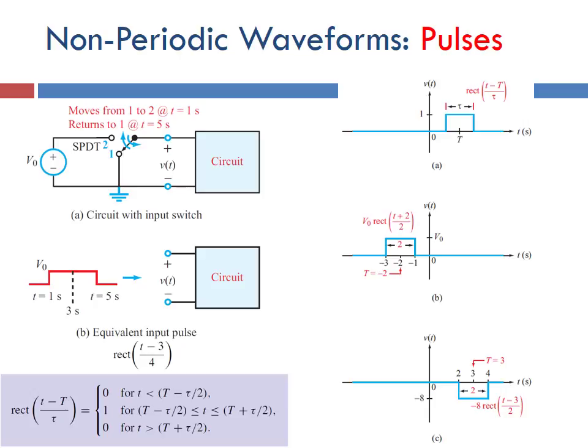and the speed of the pulse, or the pulse width modulation, they call it, PWM, changes the angle of that motor. So if you have a slow pulse width modulation, it can be 0 degrees for the motor. And if you have a fast pulse width modulation, you can have the motor move to 180 degrees. And any space in between there, you can control by the pulse width modulation, the width of that pulse, modulated to a set time period.